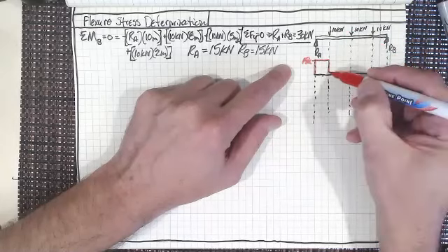Well, wait a second. We already got that. 30 kilonewton meters, I already figured it out, 2 times 15, because it's the area under the curve. So we're going up to 30, right? Does everyone see that? And this is 5, but I have it for 3 meters.